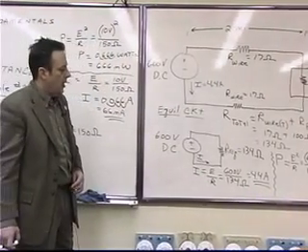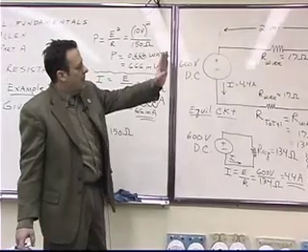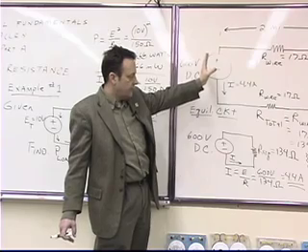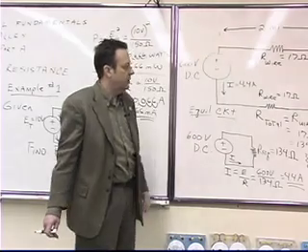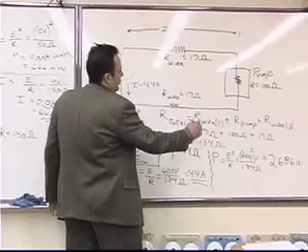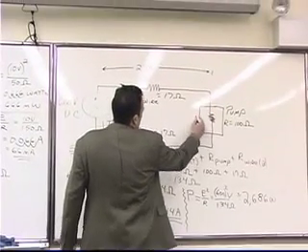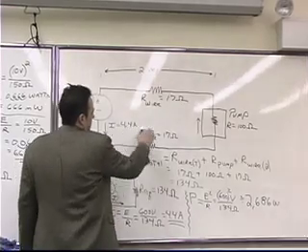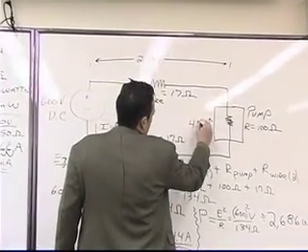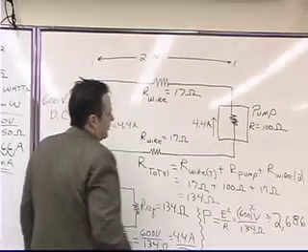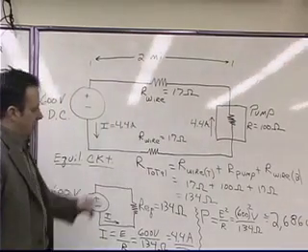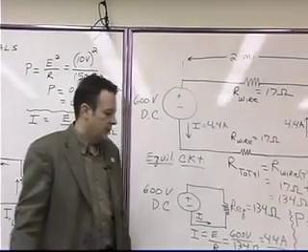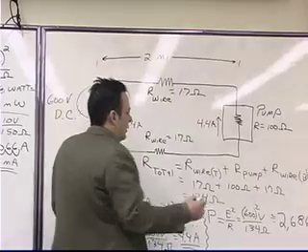All right. Now, if we go back to our original circuit, how much current is flowing through the pump? 4.4 amps. Okay? And the resistance of the pump is 100 ohms. So now we're going to use that other formula.